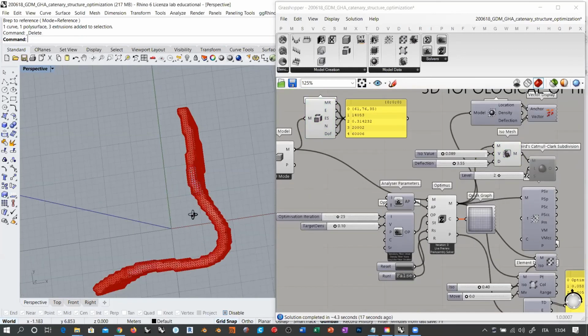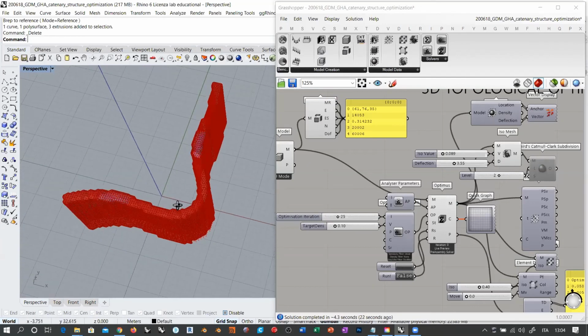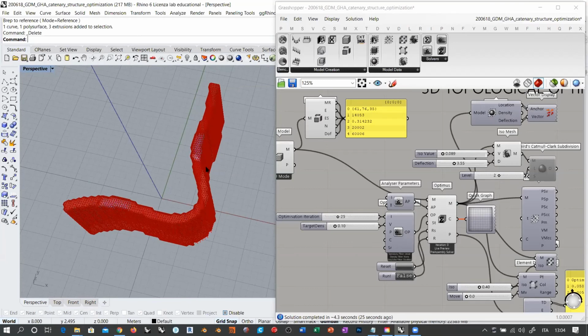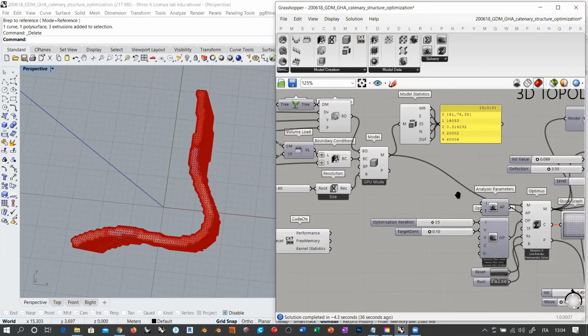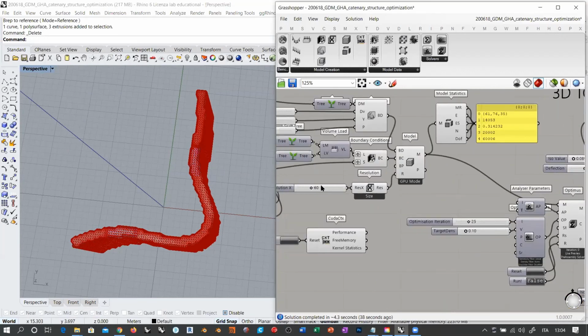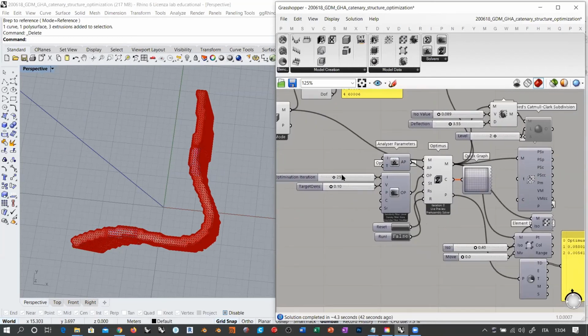You already see that it's quite low resolution if you think about it, because we have an organic shape right now, but we cannot avoid this kind of, let's say, aliasing of the edges. The only way that you can solve this is by increasing the X resolution, but I won't do this right now because that is going to be way too slow. We already have 60 and 25 iterations, so let's play fair.